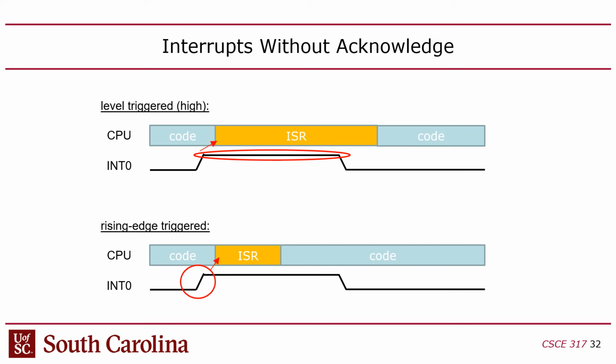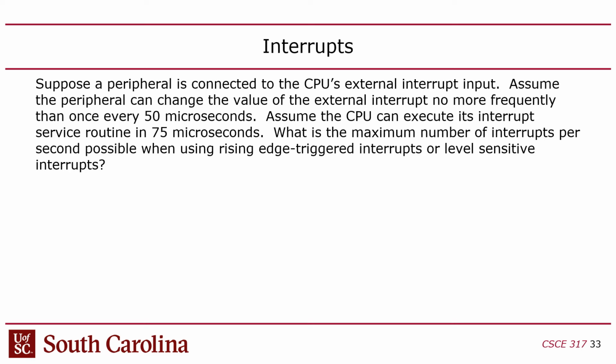Yes? So are we just going to write a little interrupt handler function and have that jump whenever there's an interrupt? Yeah, that's generally how you do it. I don't think we're going to use interrupts in our project, this is more of a concept thing. But yeah, that's what you would do. You can do that on the NIOS, in the FPGA. You can write your own interrupt service routines, and then you register them with the HAL, the hardware abstraction layer. You can do it even in assembly, just the way you load certain values into registers and then call that interrupt, and you can do it even on a PC with assembly language.